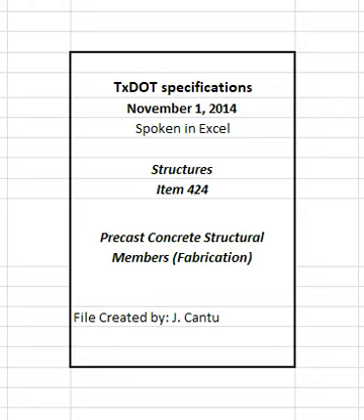The test may be performed on the entire casting line with either freshly cast concrete inside the forms or with empty forms. Provide one curing enclosure air temperature probe per 100 feet of casting line when accelerated curing facilities are being tested. Maintain the air temperature in the curing enclosure between 50 degrees Fahrenheit and 85 degrees Fahrenheit until initial set of the concrete, as determined in accordance with TEX 440A when establishing mix designs under representative temperature conditions, and for at least 3 hours after concrete placement. The concrete temperature may then be raised uniformly at a maximum rate of 36 degrees Fahrenheit per hour.